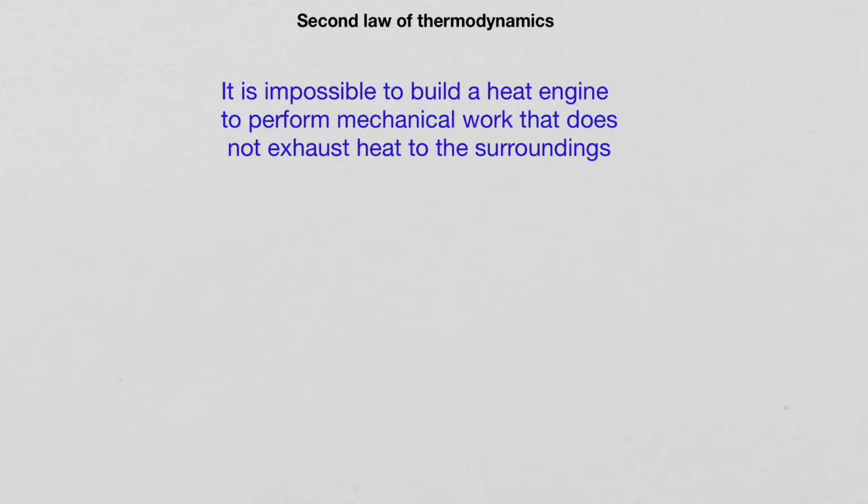The heat that is absorbed by the engine will eventually heat up the engine to the temperature of the hot region, at which point heat will start to leak out from the engine. Even if it's insulated as best as possible from the surroundings, it's very hard to stop all leakage of heat from the engine. So those two mechanisms will ensure that the engine can never convert all of the heat that is coming from the hot region to mechanical work. There will always be heat exhausted into the cold region.